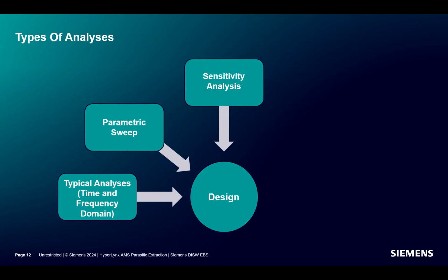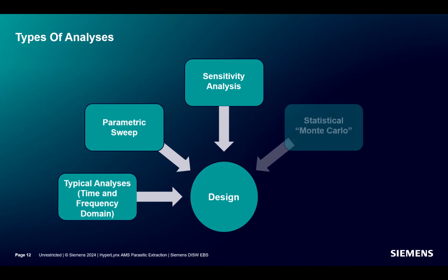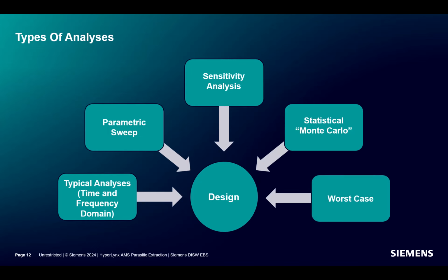A sensitivity analysis determines which design parameters most influence a selected performance metric. Monte Carlo analysis is a set of repeated simulation runs where user-specified parameter values of models in the design vary randomly with each run. Worst-case analysis runs 3 simulations, one each of the parameter sets that illustrate the worst-case upper and lower bounds, and one for the nominal parameter sets.